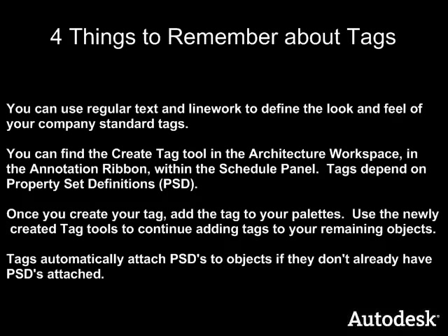So in summary, there's 4 things to remember about tags. You can use regular text and line work to define the look and feel of your company's standard tags. You can find the Create Tag tool in Architecture Workspace in the Annotation ribbon within Schedule panel. Tags are dependent on property set definitions. Once you create your tag, add the tag to your palettes. Use the newly created tag tools to continue adding tags to the remaining objects. Tags automatically attach PSDs to objects that don't already have PSDs attached.